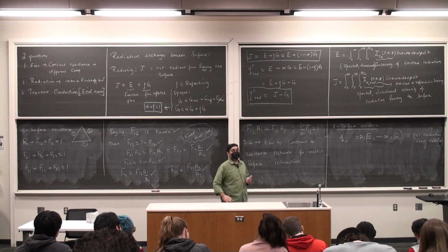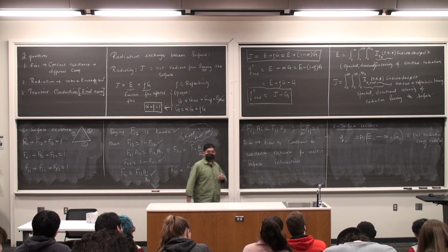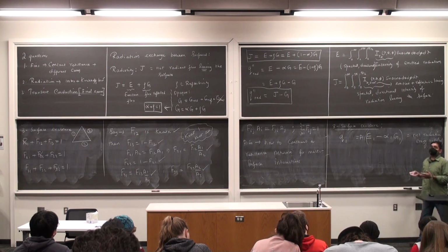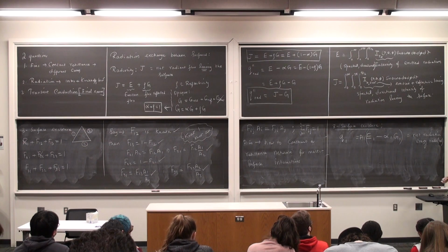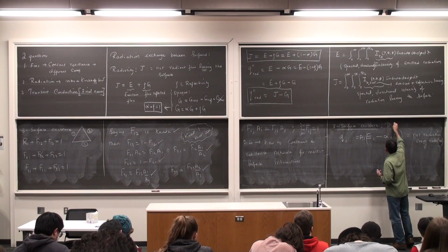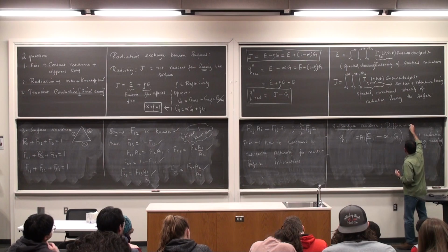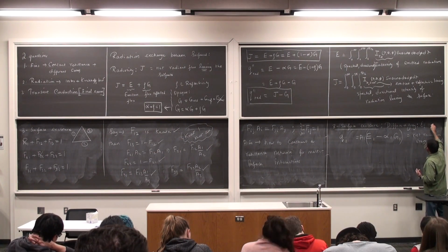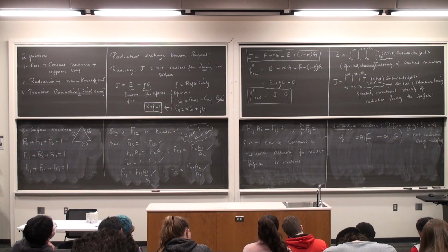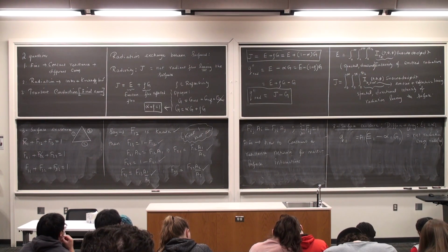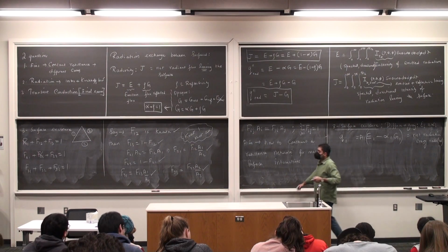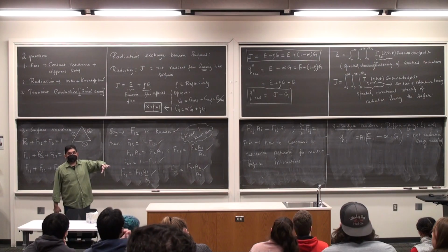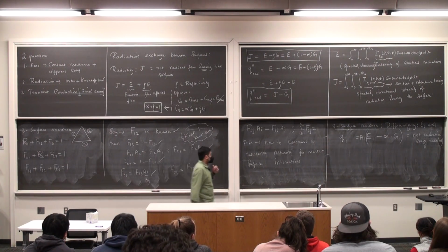If I assume that the surface is diffuse and gray, which is the most restrictive form of Kirchhoff's law, and that's what we're going to invoke today, which means that all of the epsilons is equal to all of the alphas. So I'm going to substitute for alpha 1 in terms of epsilon 1, and instead of writing E1, I'm going to write it as epsilon 1 times the emissive power of an ideal body at temperature of the surface 1.